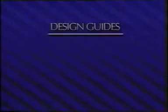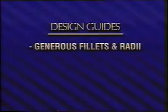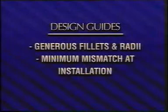Design guides that can minimize interference at the line of contact between mating parts are to provide generous fillets and radii, and to design parts with minimum mismatch at installation. This provides the lowest residual and preload tensile strains.